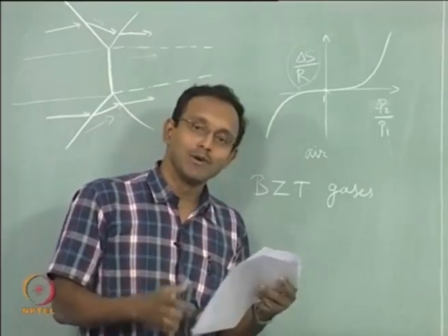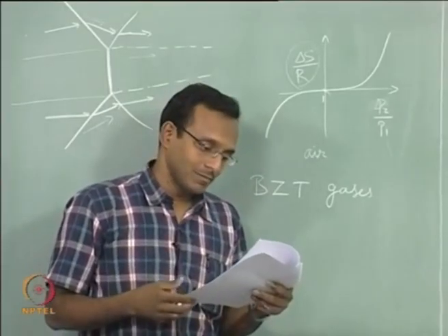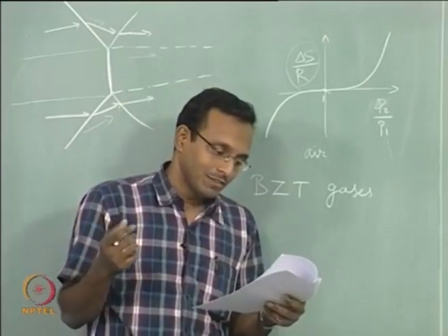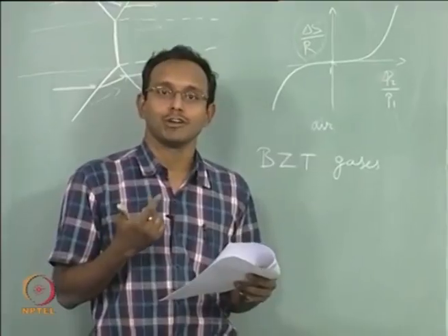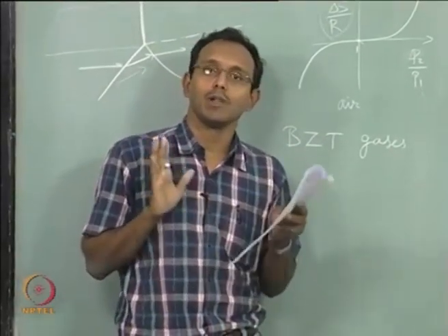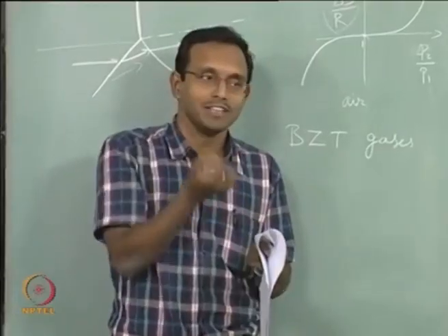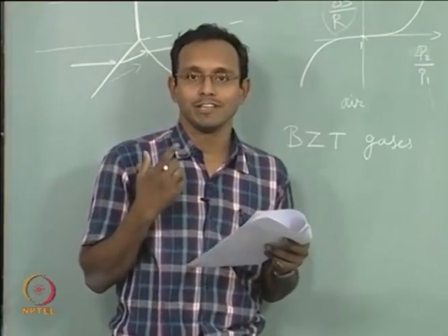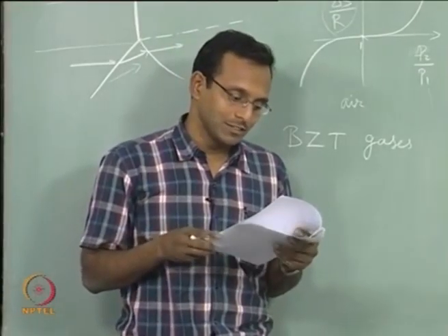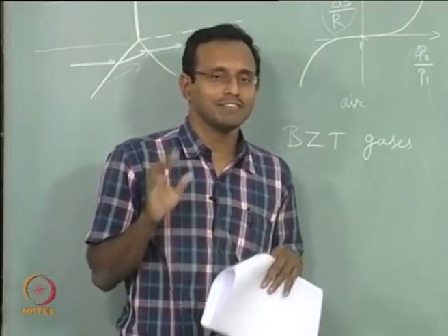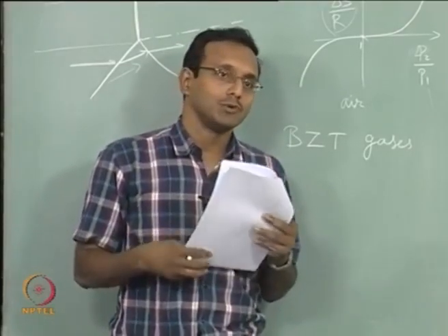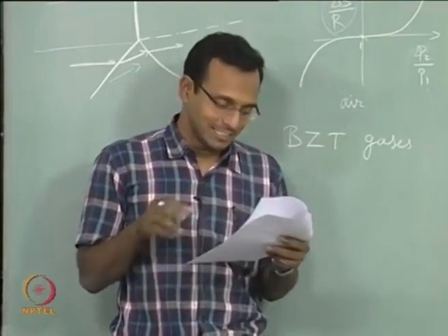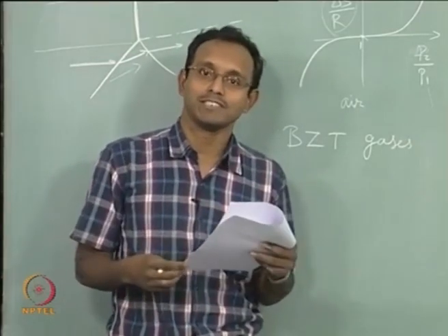Now I have to tell you one more thing which I will introduce later, but it is the right time to introduce, so I will introduce it right here and then talk about it in detail later. When I say there is a compression shock, it is a whole bunch of compression waves that come together and form a very thin layer, all one on top of each other. When it is an expansion wave, that is not the case. If I say there is an expansion shock possible, even that will be doing exactly the same thing. But it so happens that expansion waves cannot accelerate to go and sit on top of each other. We will see why after we do some expansion analysis.